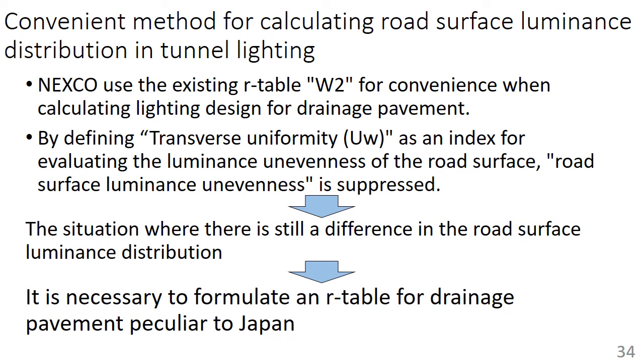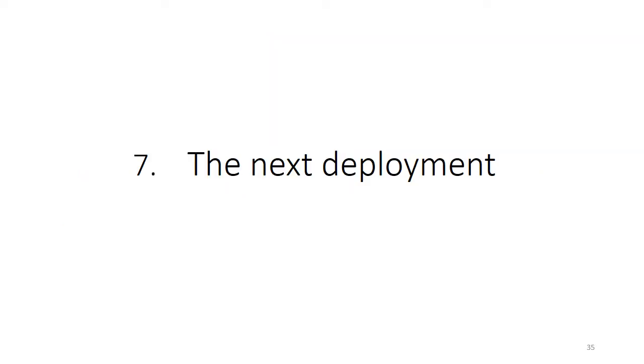However, there are still differences in the road surface luminance distribution. In the future, we believe that it is necessary to formulate an R-table for drainage pavement particular to Japan. I will explain the next deployment.